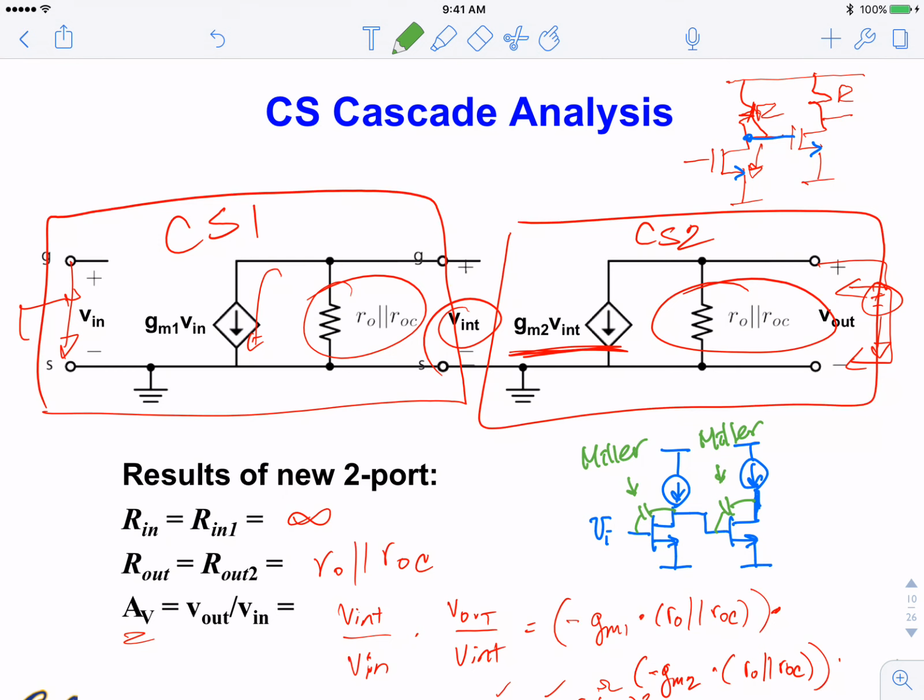It's an inductor: 1 over j omega C, and C becomes negative, so it becomes j times a positive number. There are some circuit tricks to synthesize a block of circuits that looks like an inductor instead of a real inductor. It is possible, and usually works over a limited frequency range.